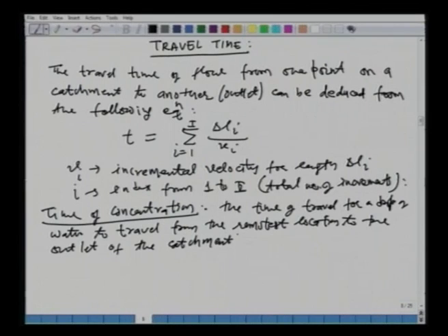If you want to look at this concept, let us say this is your catchment in which there is a major channel. Now, there may be a point on the boundary which is the remotest location. The time for water to travel from this location to the outlet, where we want to find out or estimate the direct runoff response, is called the time of concentration.